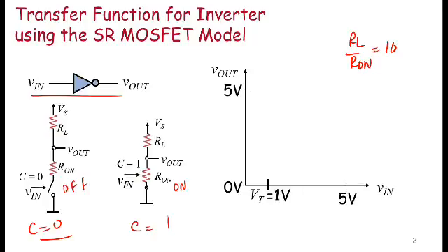Now, in general, you can look at your textbook, and the textbook will talk about how you can design MOSFETs to have various values of R on. The basic way is, just as with any element, if you increase the width of an element, its resistance decreases, so you can make the MOSFET wider, and that reduces its resistance. So the book will show you how to do this. It's not that important for 6002X.